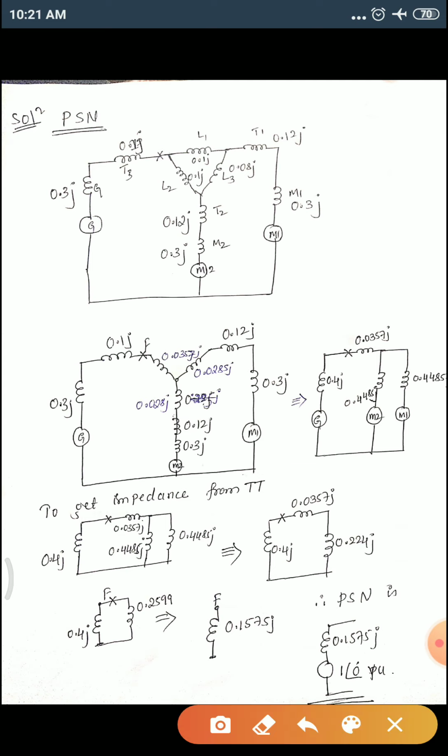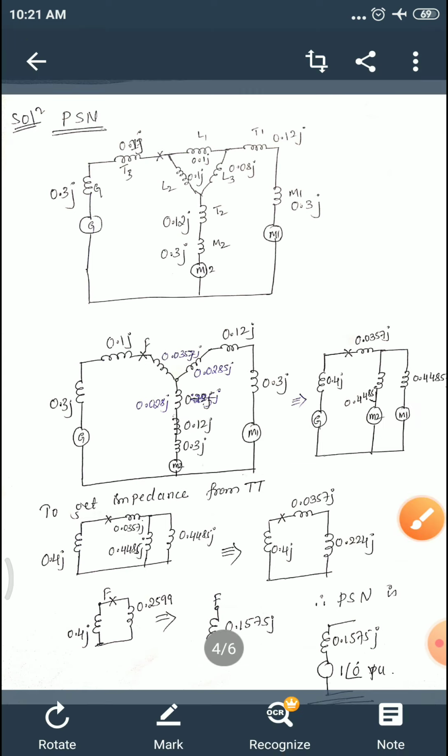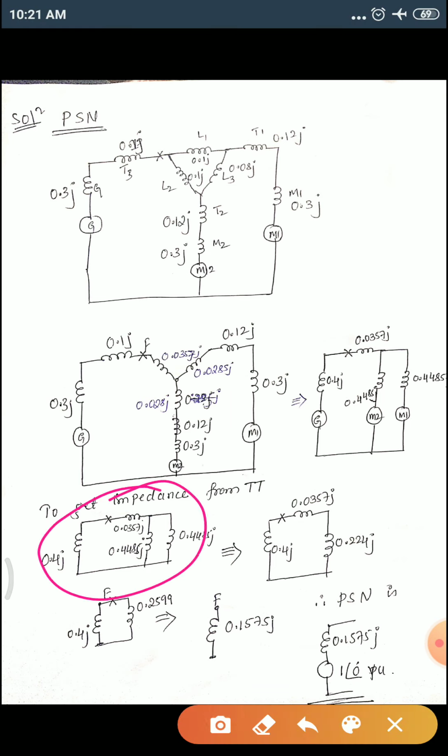To calculate that impedance, what we can do is use the Thevenin's theorem. So make sure that the sources are short circuited. Okay, since we have voltage sources, let them be short circuited. So when you short these things, it comes like this, right? Substitute all the values. Okay, so now these two are in parallel combination. Take that parallel combination, and then keep as it is this value as well as this value. Okay, and once we calculate, these two are in series, and then you can add those two and place here.